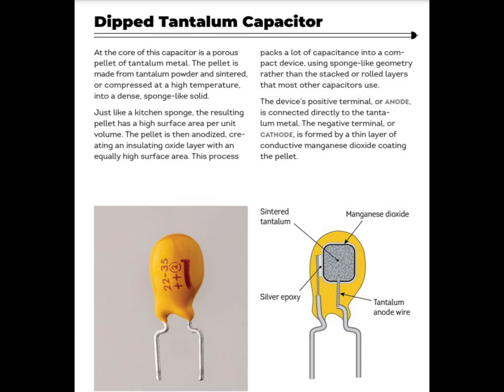It has high capacitance density, can provide a high capacitance in a compact form factor. It has good temperature stability and reliability, particularly under varying environmental conditions, suitable for high-frequency applications due to low ESR. It has a self-healing property. If a dielectric breakdown occurs, the oxide layer can repair itself, preventing catastrophic failure.